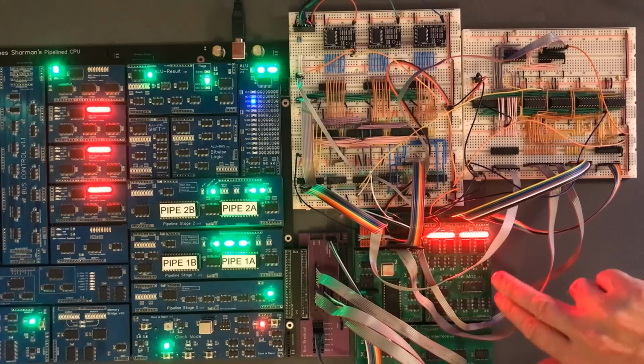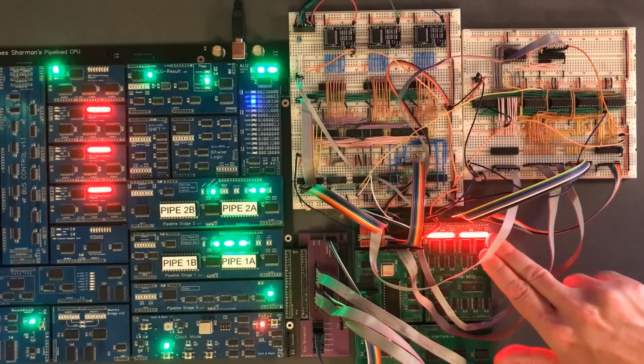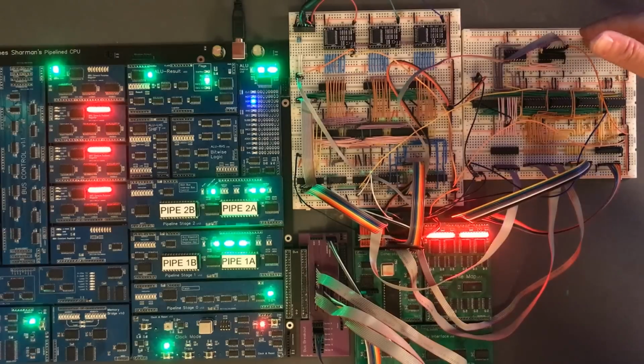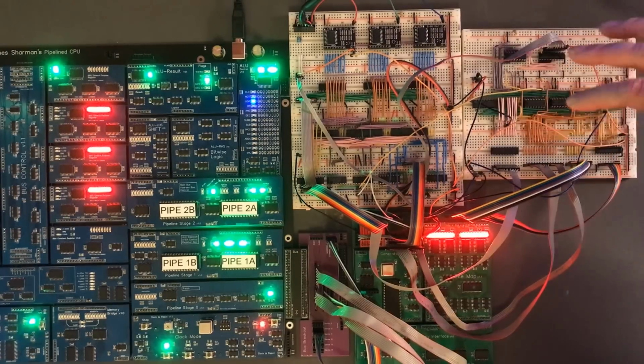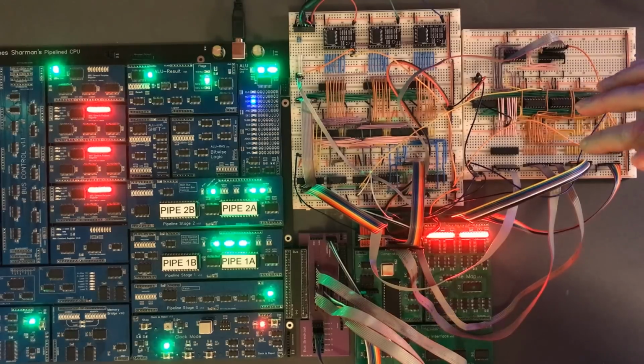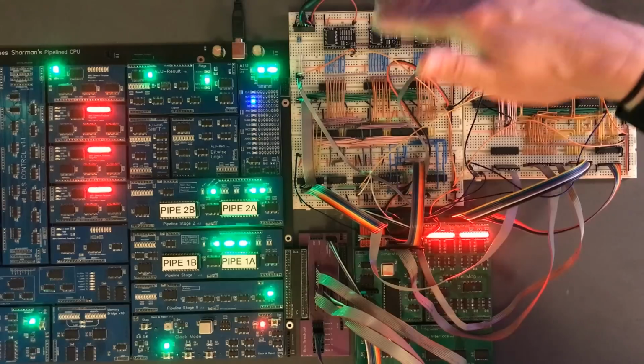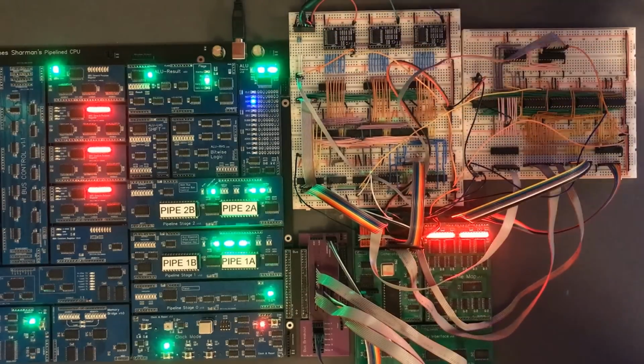Now the outputs from the tile map are the tile index and the XY position within a tile, and we pass that into the tile data circuit, which then looks up the actual pixel we want to output. That pixel is actually a color index that goes to the palette before it's finally output to the DAC circuits, and the result of those is the actual analog signal off to the VGA display.